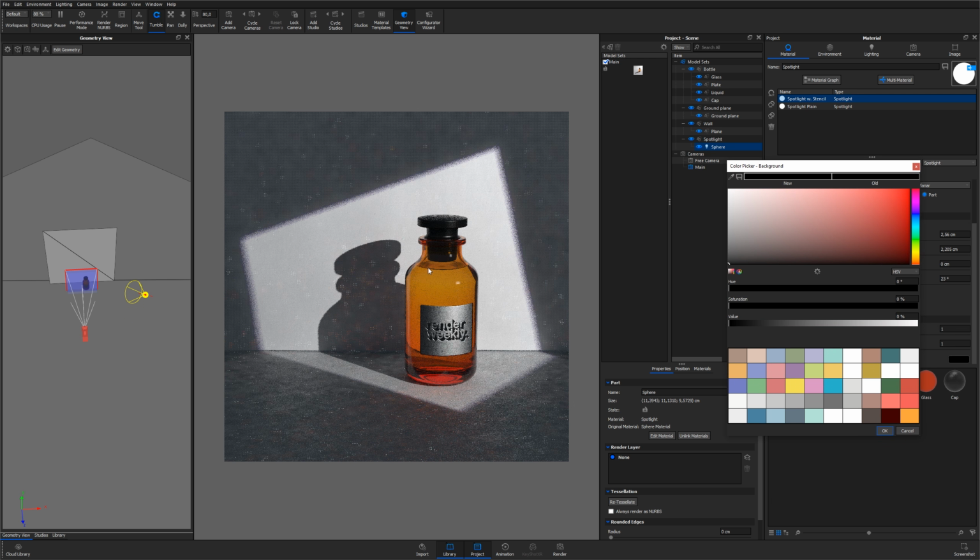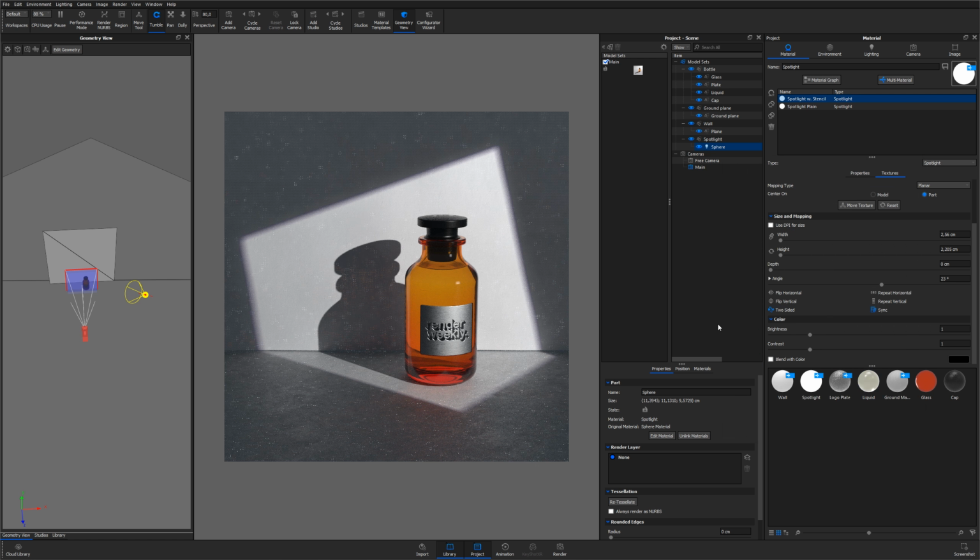So what are we going to do here as well? Again, the same workaround that we are going to use for getting rid of these splotches will also work for getting these caustics back. So this is the main lighting I want to have in my scene. The default model set, I have renamed to main. To show your model sets, you either pick this or these two arrows in the upper left corner of the scene tree, or you can take these three dots here, left click and drag it to the side.